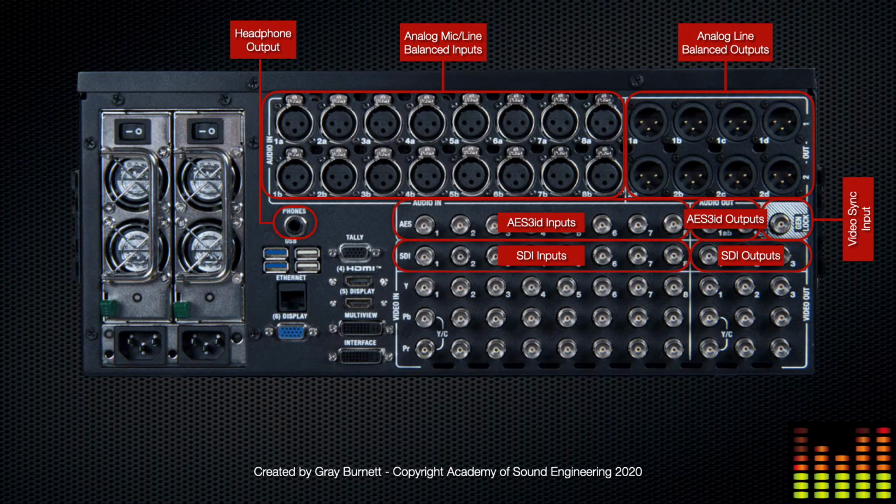We have 1 video sync input. If the TriCaster is clocked to an external video sync signal and the camera and other video equipment is also clocked to the same signal, then it is possible to have lower input to output delay through the system. If no external signal is used and all cameras are unclocked, then frames received at the input of the TriCaster are delayed until the next frame boundary cycle is reached.